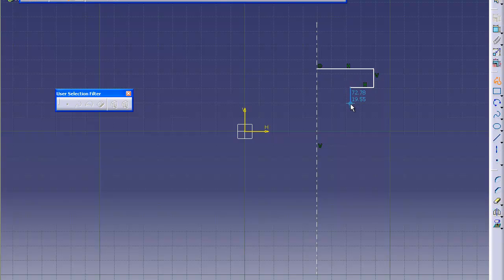Then you're going to enter your first dimensioned part, which is 39 millimeters down. You're going to go over. It doesn't really matter how far, but you have to make it coincident to this vertical line here. You can see it's coincident because of the blue line. Then just click. And you're going to go down 8 millimeters. And to the right, 9.5 millimeters. Like so. Then you're going to go vertically 67 millimeters.